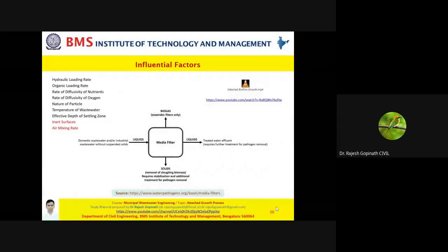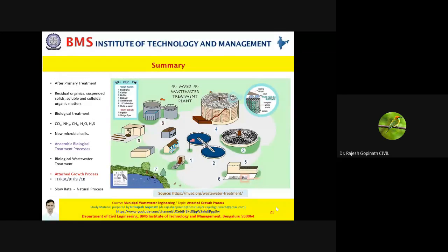So that was a quick recap of the concepts we have understood today. So what have we learned today? We understood the significance of secondary treatment. We understood the logic of biological treatment. We have realized how the waste impurities are being broken down and what is being produced. Today we also dealt with the two types, aerobic and anaerobic. And we also had a glimpse of contact beds, intermittent sand filters, rotating biological contactors, and biotowers.